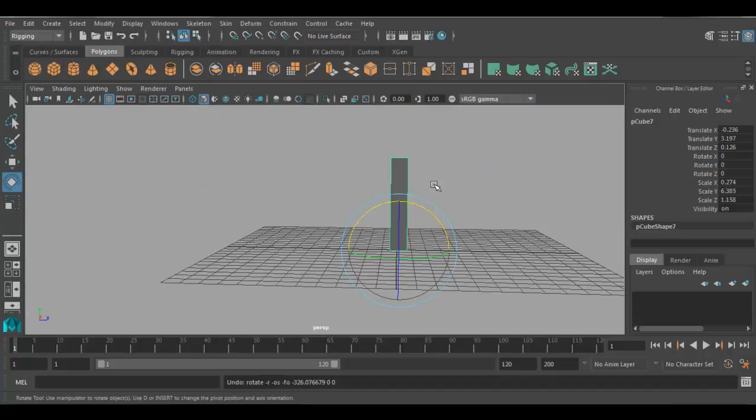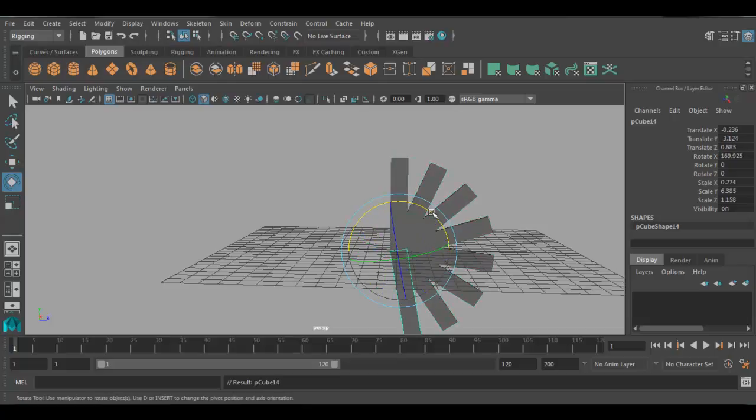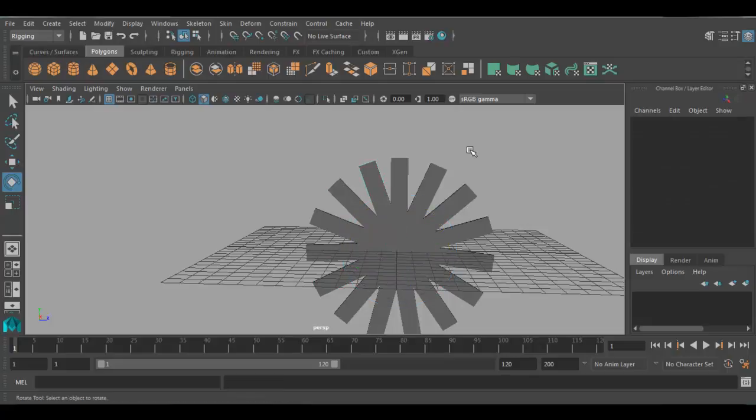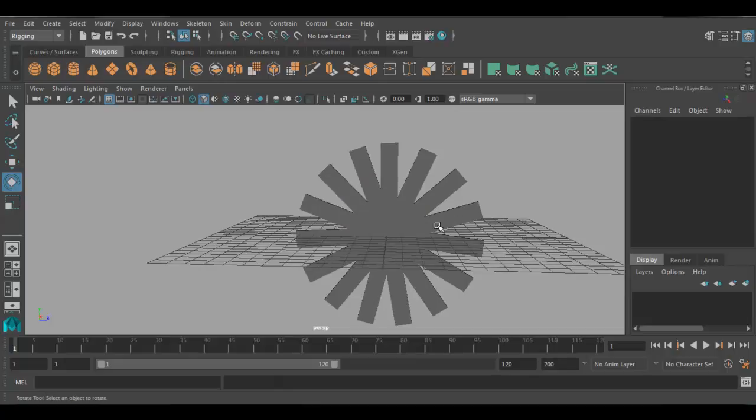Go to Perspective. First execute Duplicate command with Ctrl D. Rotate it according to your requirement. Then press Shift D. The object will get duplicated with the same angle. In next session, we will see groups.